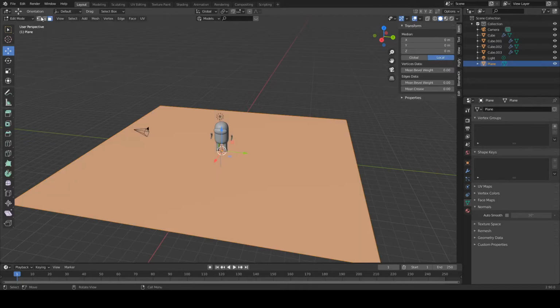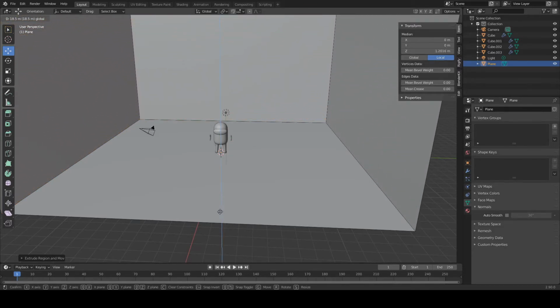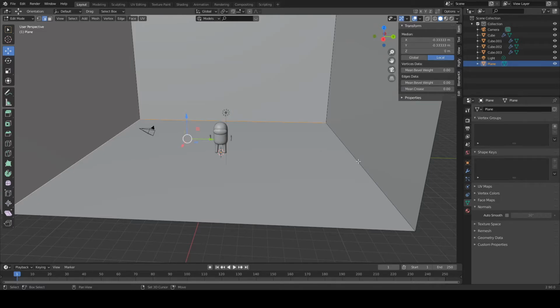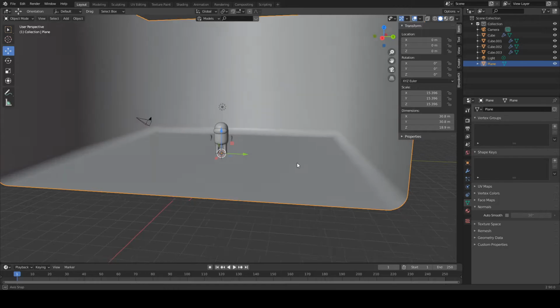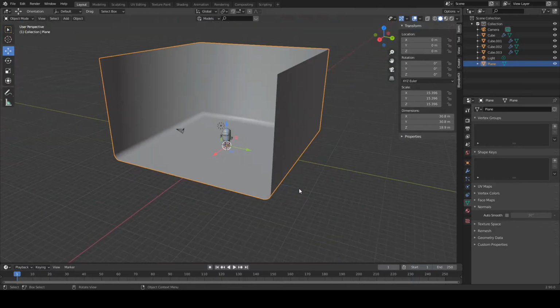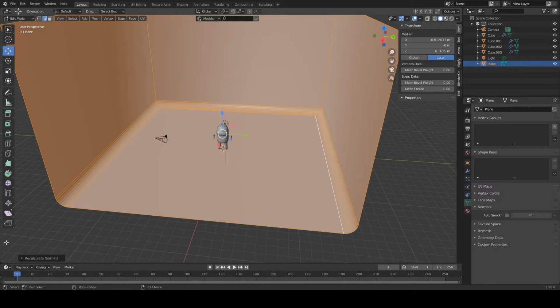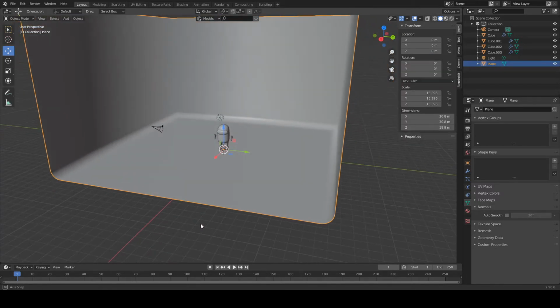Alright. Let's tab into edit mode. Let's select these three. I'm using control. And we can bring all of these up. And now let's just select these three. And we want to bevel it for that nice smooth reflection. Add in a few segments. Scale it up a little bit. Boom. Looks a bit blocky. We can shade smooth. And auto smooth makes it look a bit weird. Let's try to recalculate all those normals. Shift N, recalculate normals. Let's do them both.